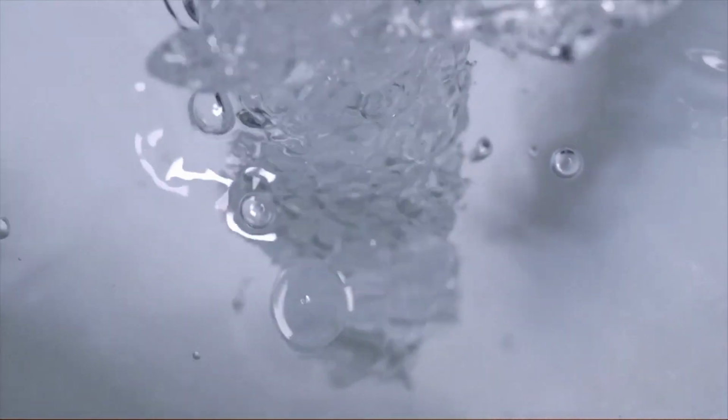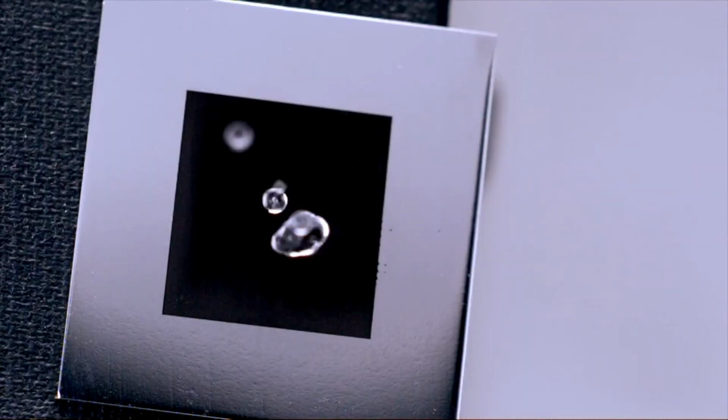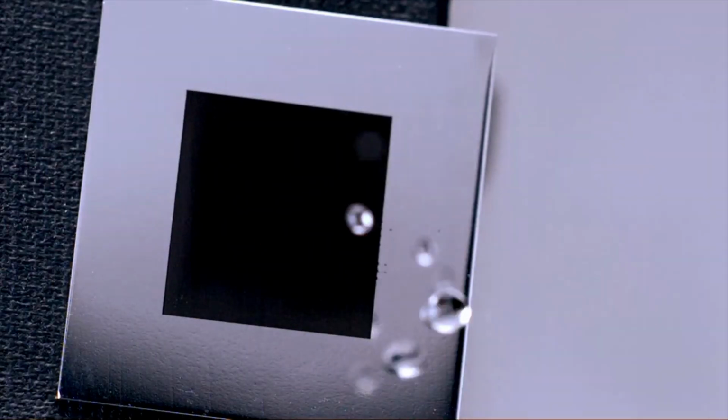But the process of manufacturing super hydrophobic surfaces is complicated and costly, and research has been carried out to investigate them. Thus, the next best option in the field to mitigate the electric field stresses on polymer insulators is by maintaining hydrophobicity of the insulator, which incorporates the optimum contact angle of the water droplet. This project is focused in this manner and objectives are achieved.